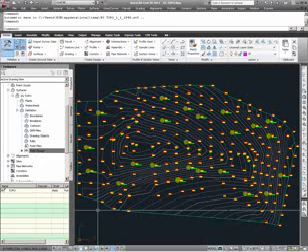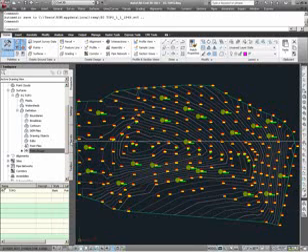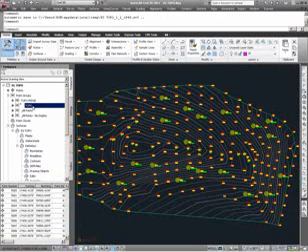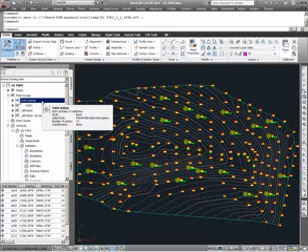As we get started, I will first say that the break line we will be creating for this surface will be the break line that represents the ridge points that have been surveyed for this topographic surface. As previously mentioned, from the topo point group, the ridge points belonging within that group were extracted and created in what you could say is a sub-point group. This topo ridge point group contains just the ridge points.